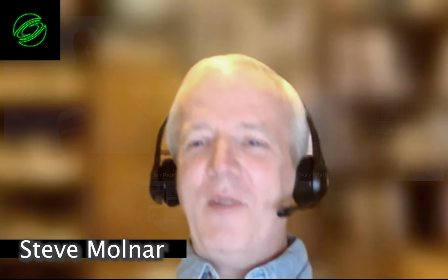In fact, Steve, you might be the right person to say, what was the jump from Pixel Planes 4 to Pixel Planes 5? Well, as Henry said, with this rendering algorithm, the first thing that you do is you figure out what pixels are within a given triangle. And when they're small, you just exclude everything. And now you're just working on a small number of pixels. So what we decided to do to improve the utilization was to tile the screen. So the next generation, Pixel Planes 5, you could decide the number, but a number of tiled rasterizers.